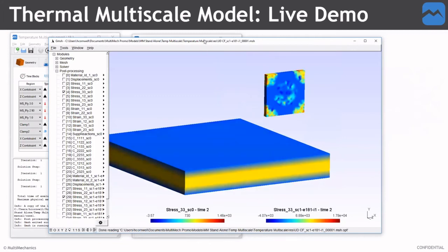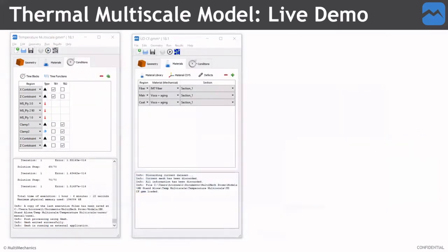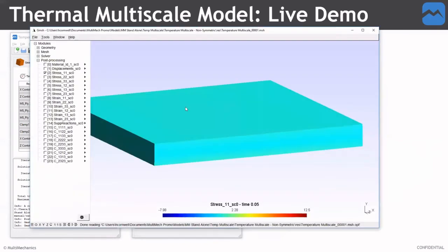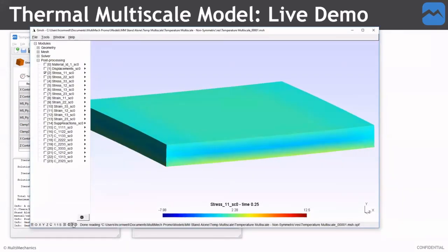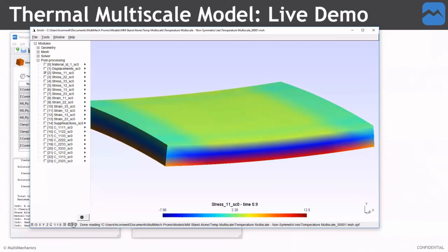So we can use this capability now for looking at residual stresses within a symmetric flat layup. We can also do more complex geometries, such as non-symmetric layups for whatever reason. You can start looking at how the geometry will deform as it's being cooled down. And I'll show that through another example that we did. In this case, we only did 2 plies, one at 0 and one at 90. And we did the same exact cool down. And we can start to see the deformation of this plate.